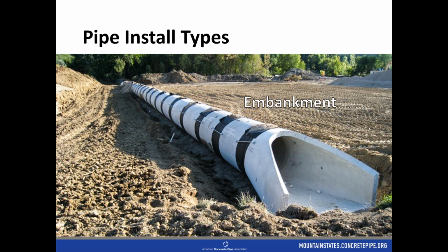If we do have a trench detail, sometimes we can do a special design. If it's close to a class and we want to know exactly how much load, we can actually run a program. We talked about it in our January presentation, but we can do a special design for trench if we want to make sure that we're getting it as accurate and as detailed as possible. So that is an option if the fill height charts aren't going to work for us. If it's too high of a class, we can always look and see what a difference it would make if we did the installation by trench.